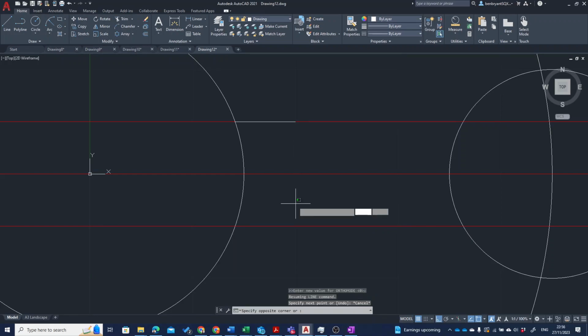So I'm going to overrun and trim. So line, lock that to 90, overrun slightly. Click TR to trim that back. Mirror, and just choose the 2. Lock it at the bottom, so mirror around the bottom point. Push it up in this case.